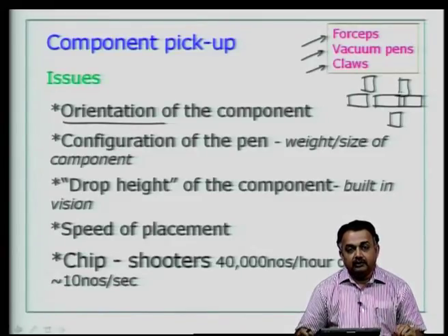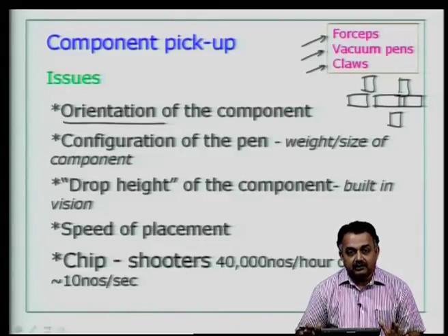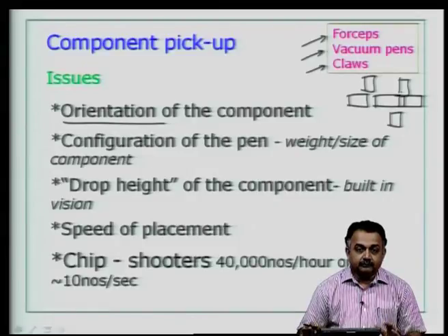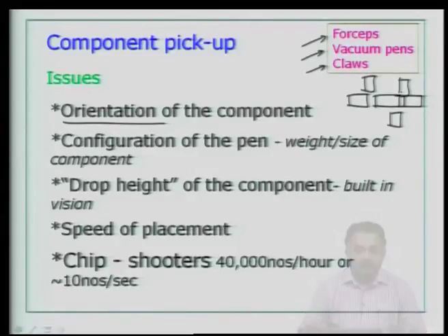As far as pick and place is concerned, you have to have a very good design vision, so that your placement process has high yield based on orientation, based on the pad sizes that you have defined for your SMD devices and so on. We will talk about surface mount device sizes and dimensions.